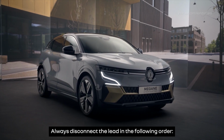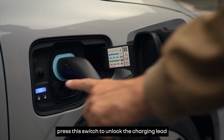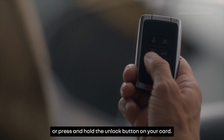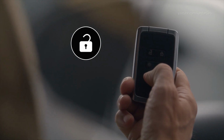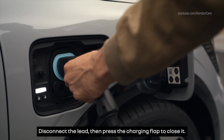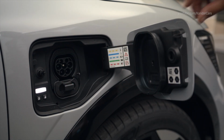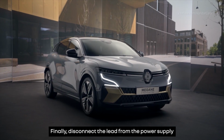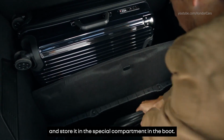Always disconnect the lead in the following order. Press this switch to unlock the charging lead, or press and hold the unlock button on your card. Disconnect the lead, then press the charging flap to close it. Finally, disconnect the lead from the power supply and store it in the special compartment in the boot.